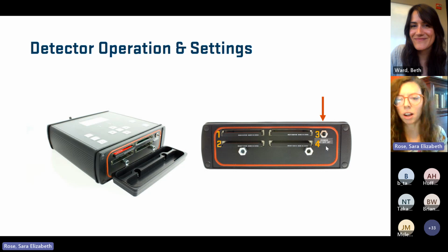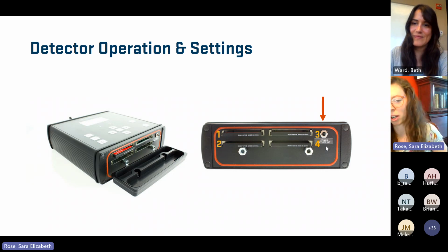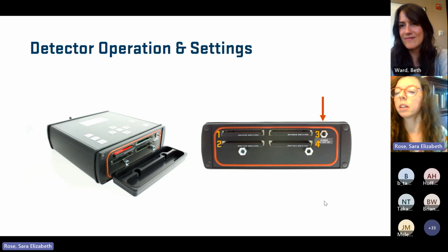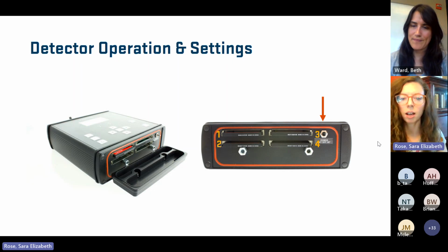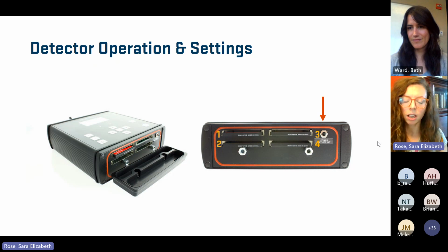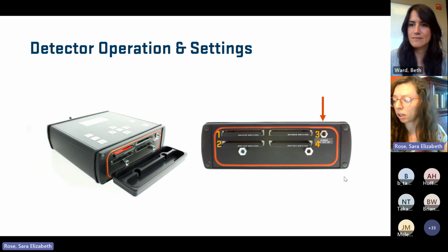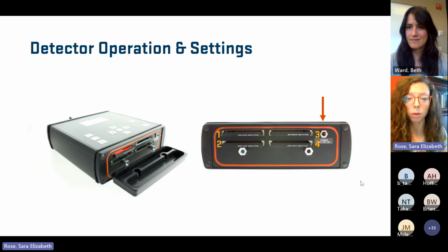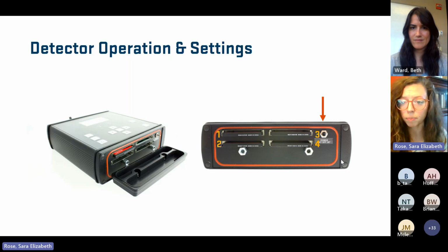Okay. I'll just start fresh from putting the cards in just to make sure that we're not missing anything. Sorry about that, guys. My Wi-Fi is usually good at the house. Anyways, installing the cards, you're going to remove that bottom plate. And then you always want to start with that upper left-hand slot. Then you go lower left, then upper right, then lower right. The order in which you put cards in the detector is numbered in that image.